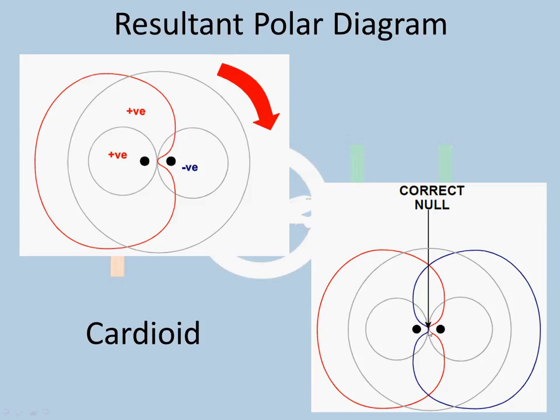But the problem is, you cannot have a rotating loop aerial loaded on the outside of the aircraft. So an electromagnetic circuit is used to make the loop feel as if it's rotating, by switching circuits and logic circuits, and hence this resultant polar diagram comes into play. And that's how the bearing is depicted on the RMI or the RBI.